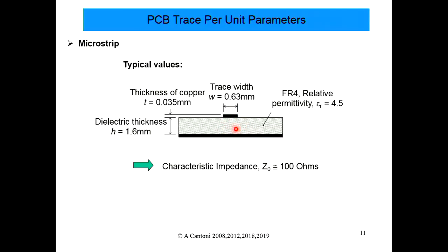effectively the signal wire interacts with the ground plane over some short area underneath it, okay? Because these distances are really small, so it's typically 1.6 millimeter thick here. This might be half a millimeter wide, okay? And it's only interacting here. So all the signal wire sees is just this constant ground plane, okay? So the actual impedance and everything it sees looks uniform over the whole length of the line, okay? You don't see any changes, okay?